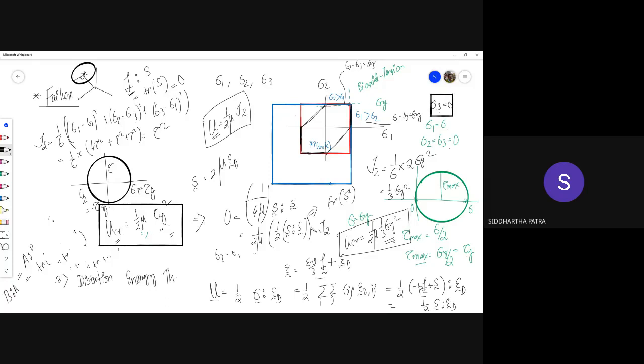So both are expressions for the critical distortion energy, which basically means tau y squared is 1/3 sigma y squared, or tau y is 1 by √3 sigma y. Okay, so very familiar expression.